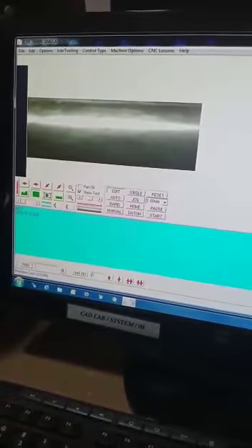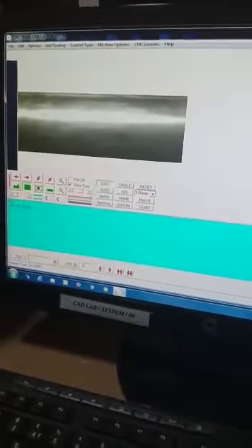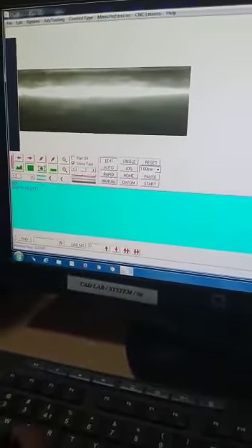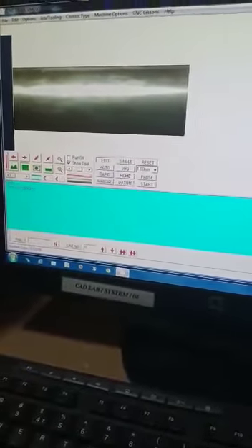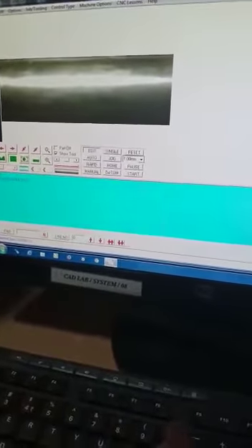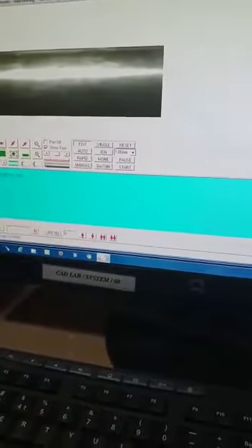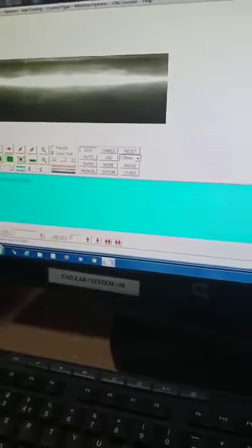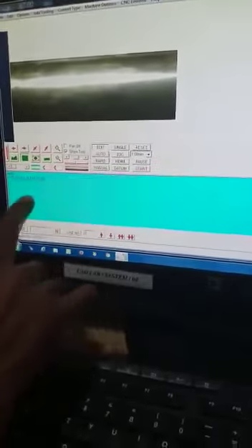G28. This is your positioning, rapid traverse. And then if you have to put a feed, depending upon this you have to enter the feed, 1000 or feed 10, like this you have to type it with a space, and then spindle speed S1000 RPM, and then enter. So like this you have to type it here at the bottom. Every line you have to make as one block. This is the area where you type the program.